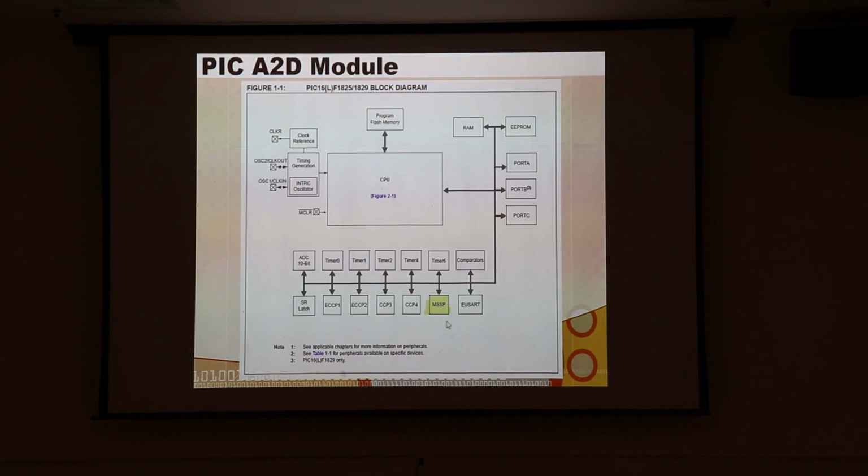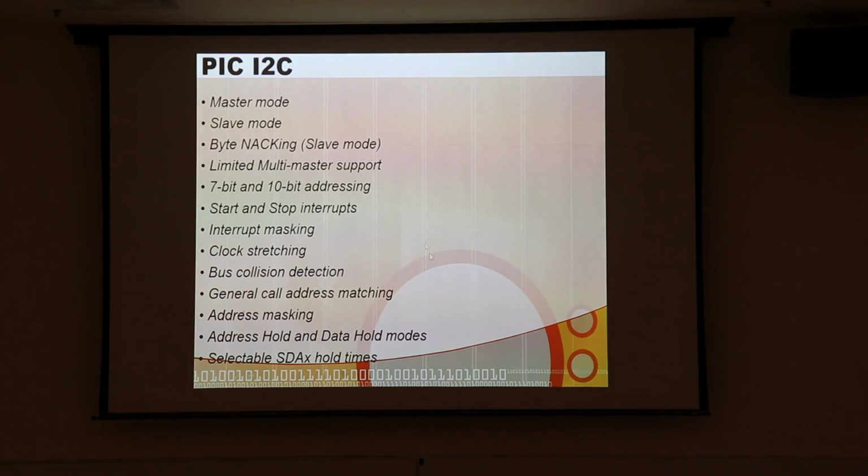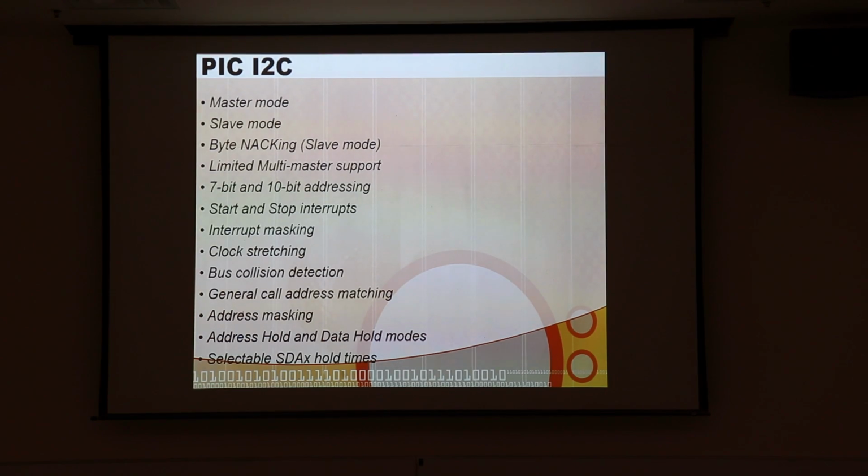So here's the master synchronous serial port, and there are 2 of them, 1 and 0, on this chip. The I2C is a pretty full-featured I2C module. It can be master, it can be slave. In slave mode, it can do byte acking and nacking.